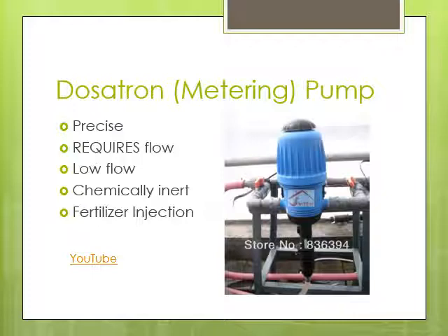I think we know enough about these to know that they are present in greenhouses. They are very popular. It's going to be way easier for you to watch the video to learn how they work than for me to try to describe it. Unfortunately, we can't take it apart, but you'll get a pretty good sense of how the pump works when you're watching the video. What I will tell you is pay attention to the video. At the very bottom of the nozzle here, there's a little check valve. And in my experience, it's that check valve that actually causes the most problems when your dosatron stops working.